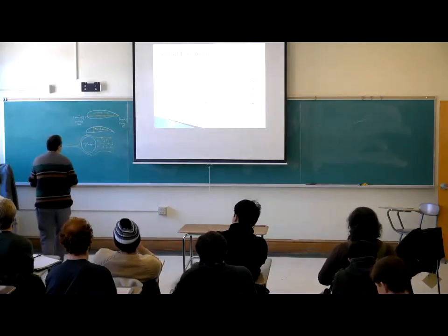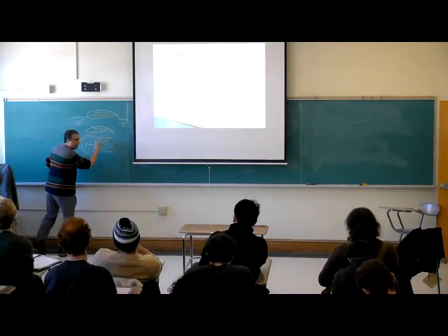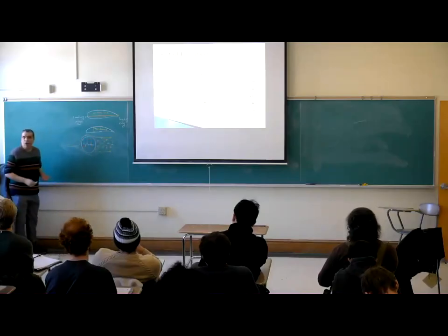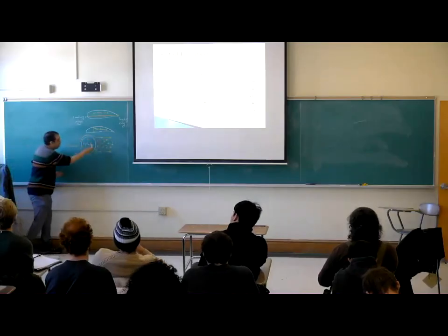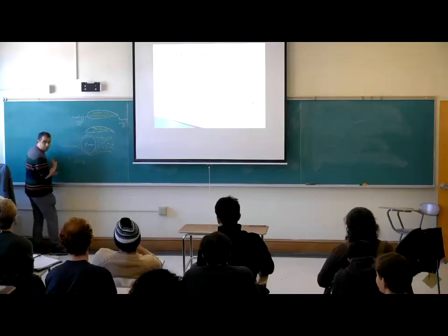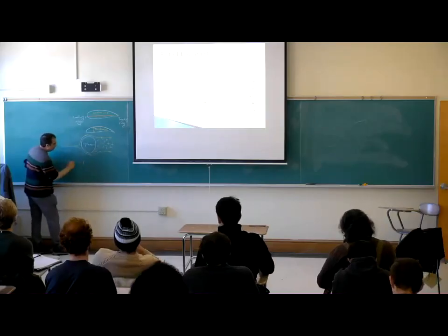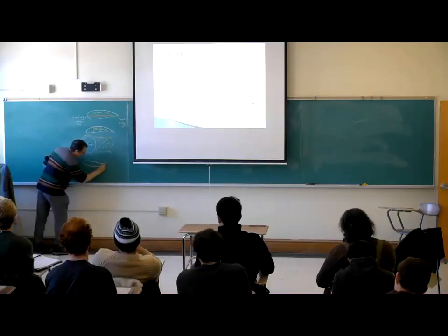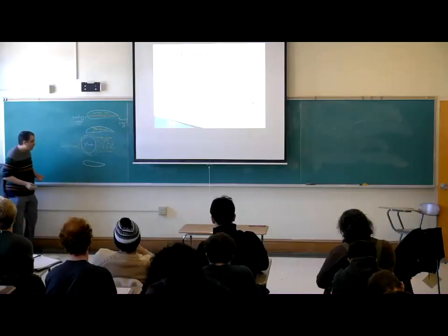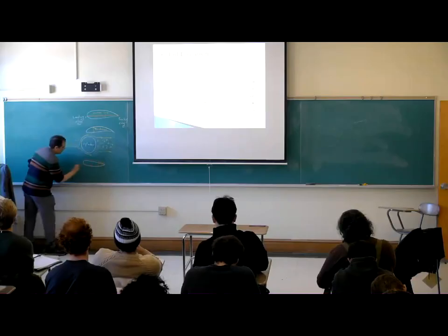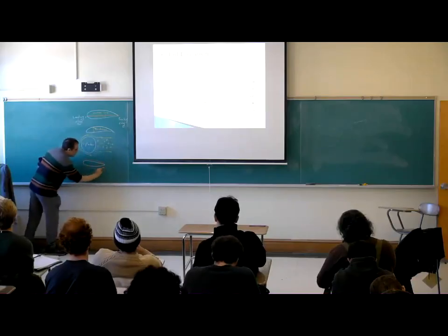So they said, in order to avoid these vortices, we shouldn't have a very sharp cylinder. We should have some turning point at the leading edge, and then make it like this. If we make it like this, the flow moves very smoothly over the body.